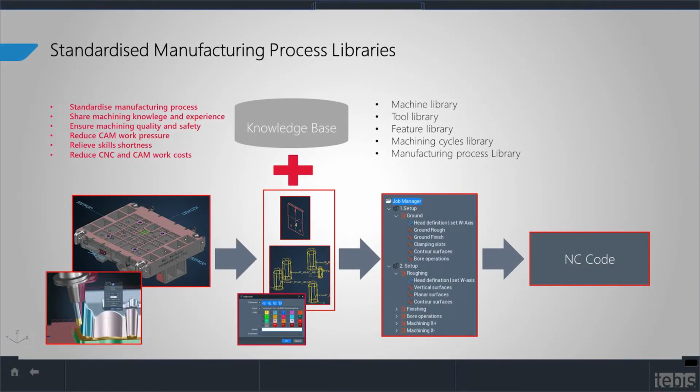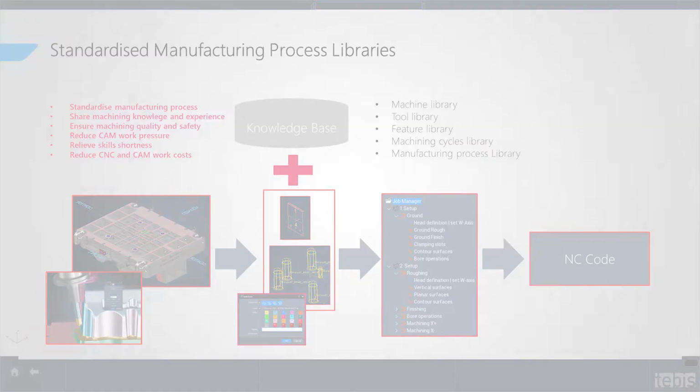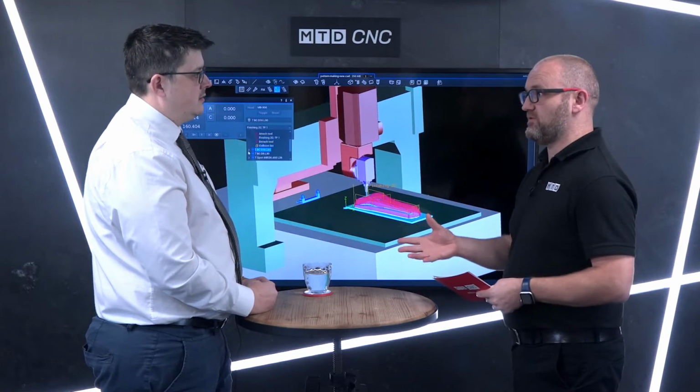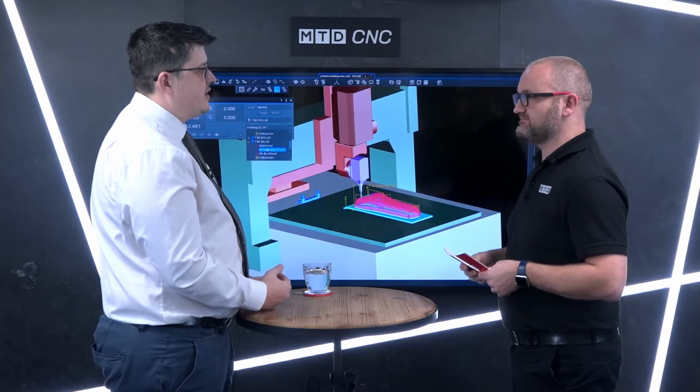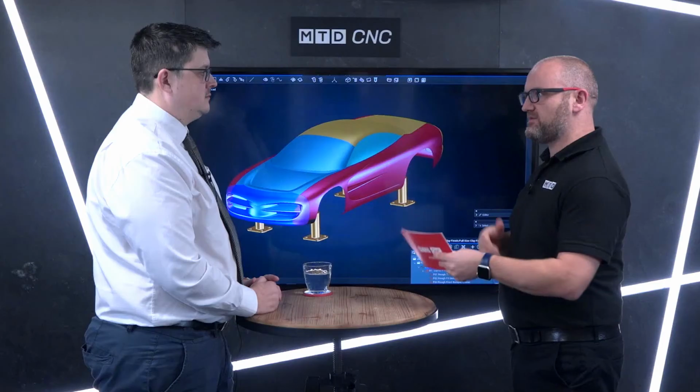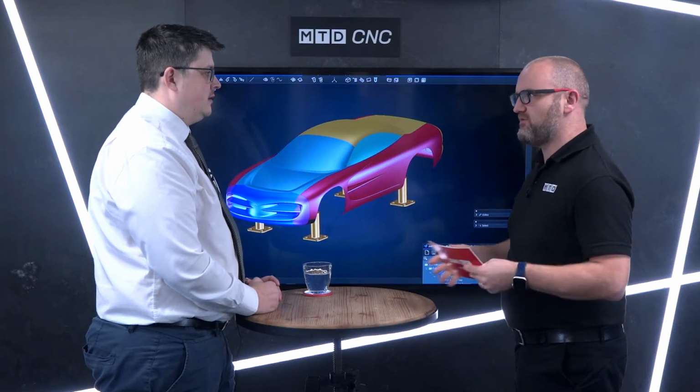The template is also able to incorporate our feature recognition technology, and then also apply NC sets, which are another level of automation when predefining machining processes. And because you scan the machines essentially, don't you? You know what it says on your computer screen is essentially what's going to be output onto the machine and ultimately the finished component. Absolutely. All of our automation technology working hand in hand with our virtual machine means that we should get a good program right first time. I can see this will be quite straightforward for 2D, 3D objects, but how about simultaneous 5-axis machining? Is it still achievable?